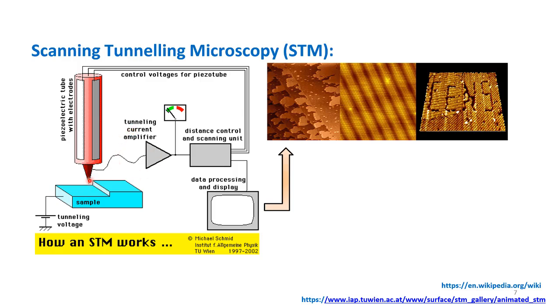And again, suppose I kept the height as 10 nanometers, so it will adjust the height when it comes closer to the sample, and then we will be able to get the information. So like this, we will be able to get the information. And one more thing is the current. If I keep the current value constant, in that case also it will not damage the tip, and the scan will give the information about the surface.